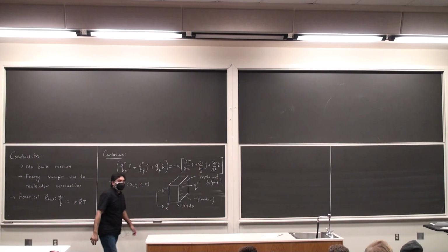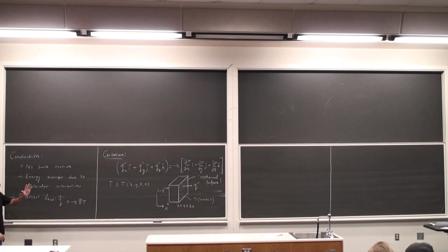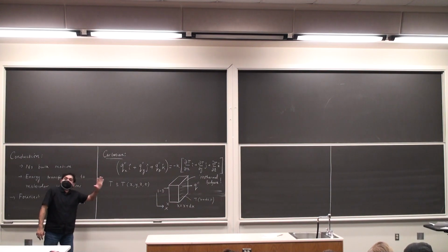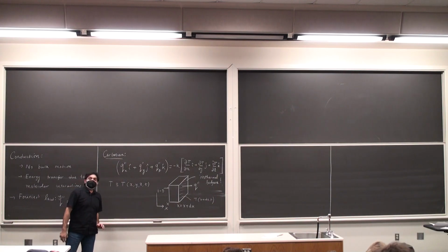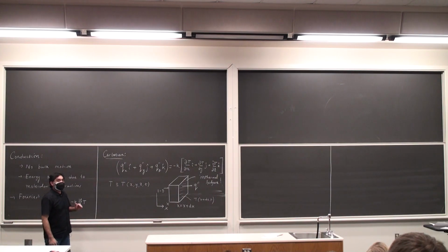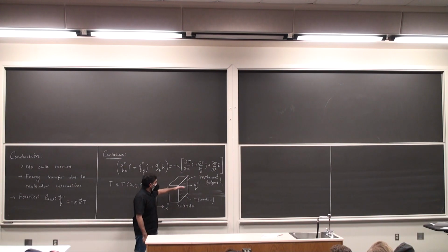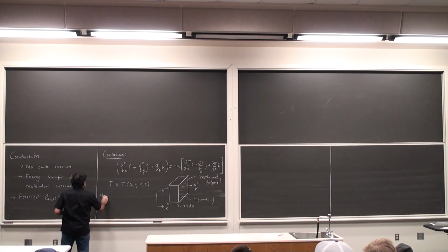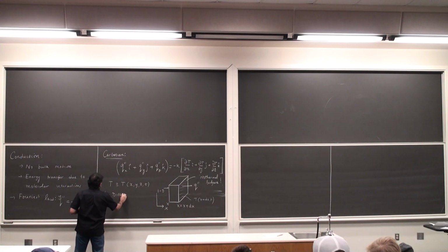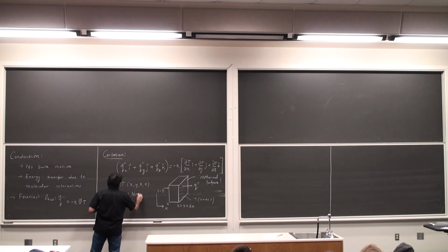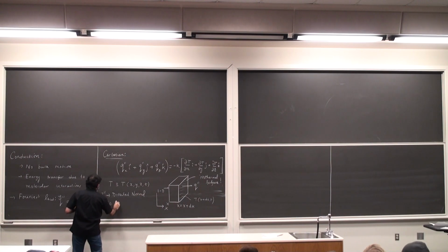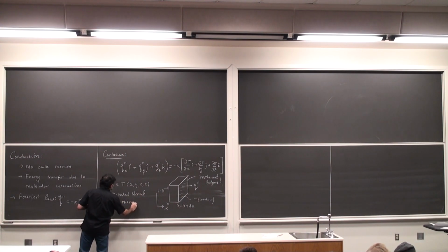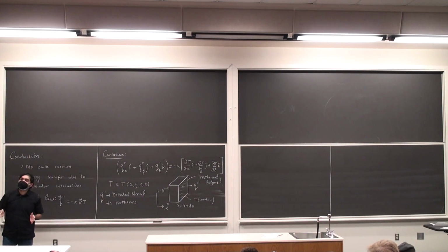And so this tells us a very important point. The direction of conduction heat transfer is along the normal to an isothermal surface. It's left or right or right or left, I don't know, it depends on the temperature distribution, of course. But the underlying point is that the direction of q double prime is normal to the isothermal surface. So q double prime is directed normal to isotherms, which are lines of constant temperature.